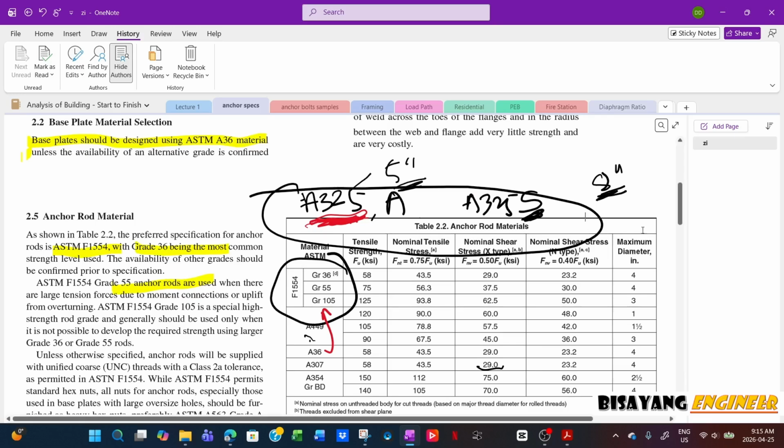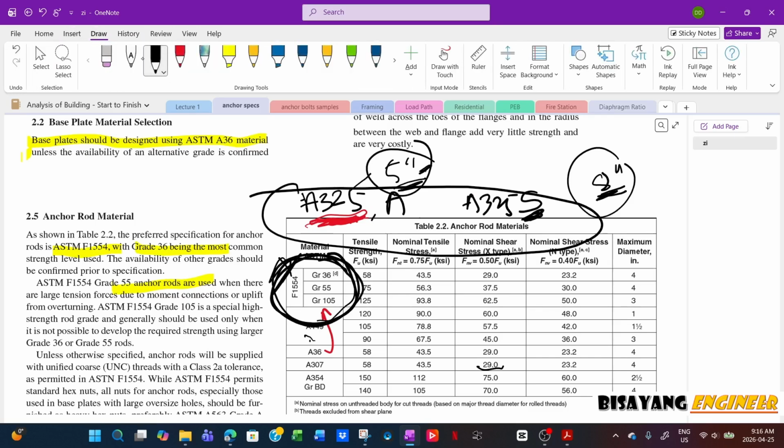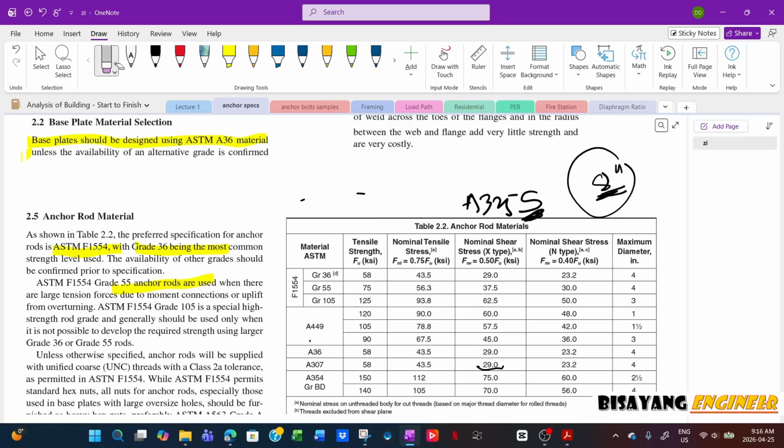So that's why it is not used, because if you consider the projection, for example in a steel building, your projection is 2 inches or 3 inches, and then you only have about 2 inches left for embedment, which is nothing. Also, these materials are tested for that specific application. So that's why it's better to just specify whatever is stated in the design guide.